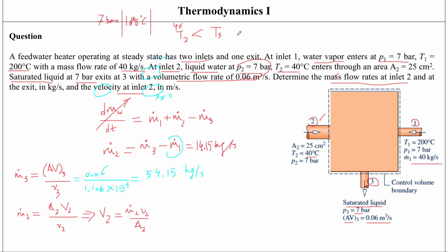And for a compressed liquid water, we've already discussed that to find out this specific volume, we can just go to basically the saturated liquid table that is of the temperature form, and we just take out the value of vf, which is the saturated liquid specific volume.